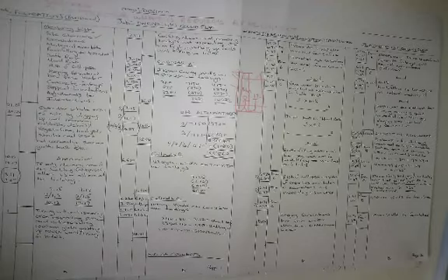It's not prescribed to work after it has rained, because you still need to dry up. It's not prescribed to do any concrete works when you've got a soggy, field of mud type of trench. You need to let it dry.